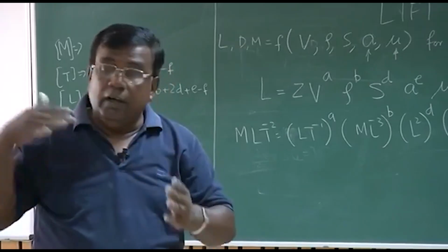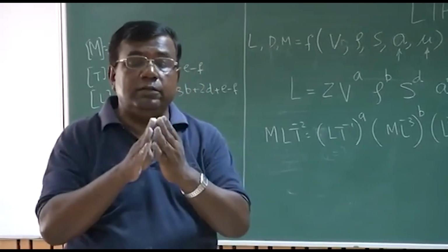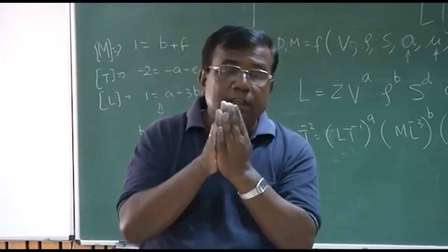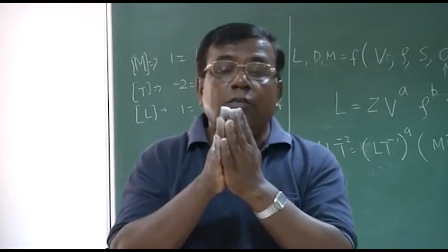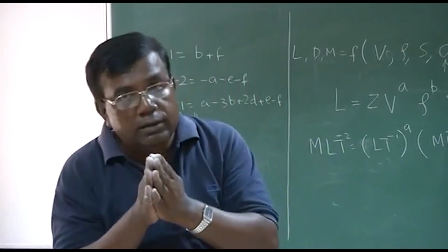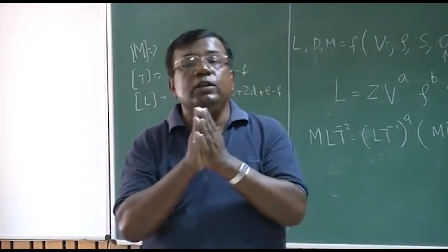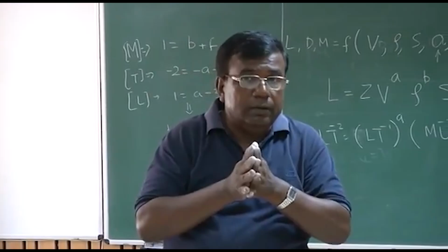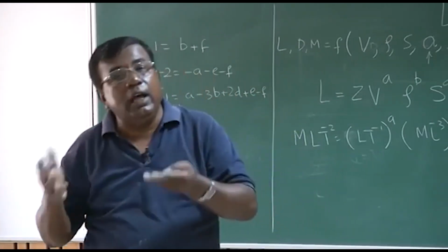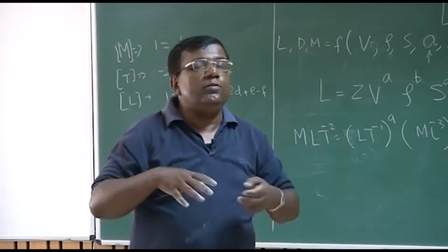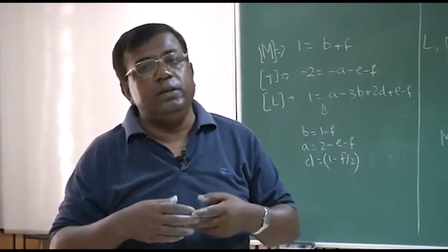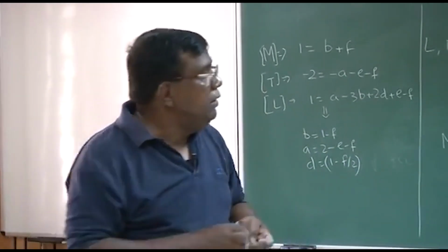So because now the velocity of the body is more than the velocity of sound, there will be a compression. And that compression means a lot of energy it has absorbed from the vehicle, and hence we say it will increase drag, or we say there will be formation of a shock wave. And the shock wave again will interact with the body, and it will again redistribute the pressure distribution. So it will have different effect on lift and drag, right?